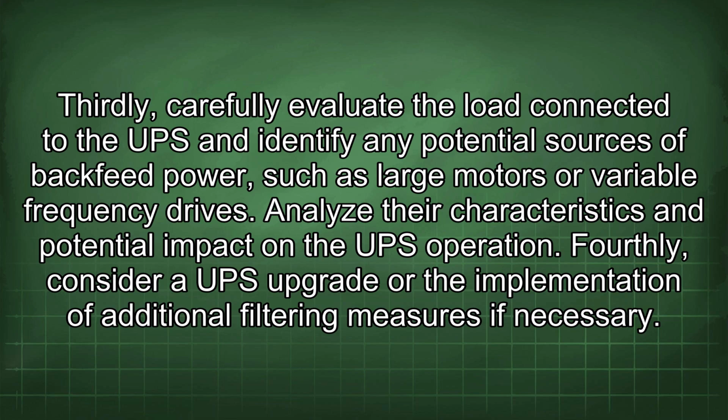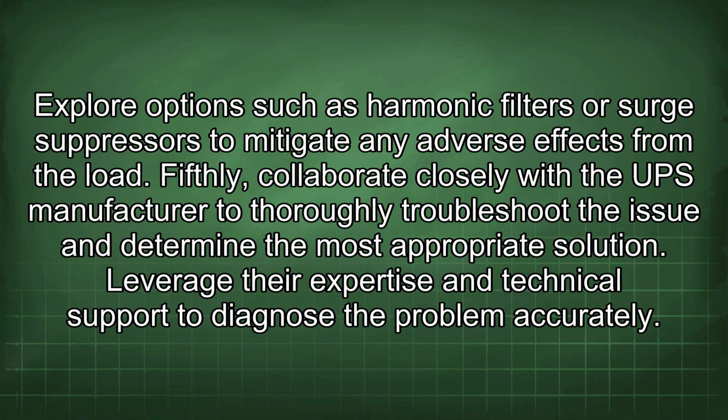Fourthly, consider a UPS upgrade or the implementation of additional filtering measures if necessary. Explore options such as harmonic filters or surge suppressors to mitigate any adverse effects from the load. Fifthly, collaborate closely with the UPS manufacturer to thoroughly troubleshoot the issue and determine the most appropriate solution. Leverage their expertise and technical support to diagnose the problem accurately.